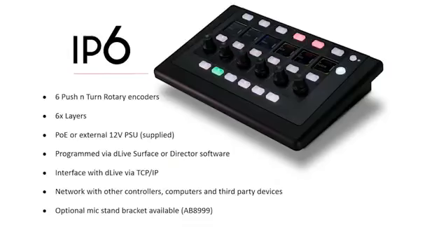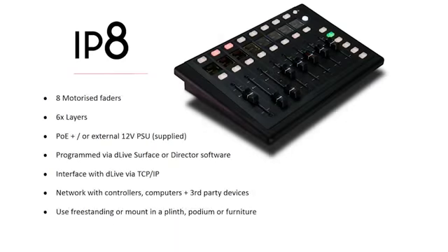The IP8 comes with 8 motorized faders, 60 mil motorized faders, and again 6 layers. So in this case, you can access up to 48 discrete channels or masters. It is compliant with the PoE Plus standard. That's the highest of the two standards of PoE. So if you're buying a third-party switch or PoE injector, make sure that it complies with this standard. And again, you can use it freestanding or mount it in a plinth or any installed furniture.